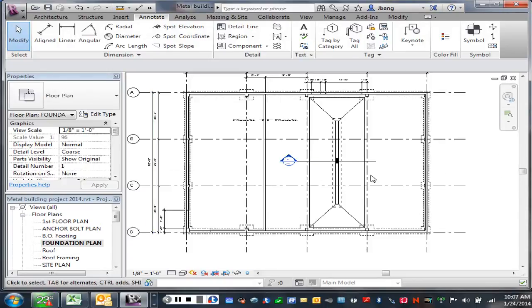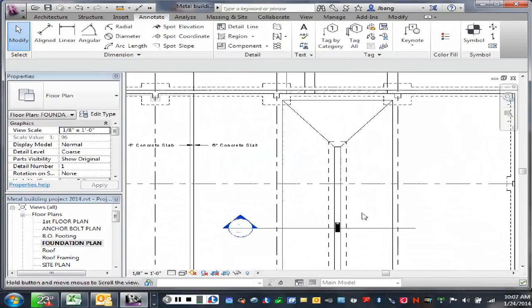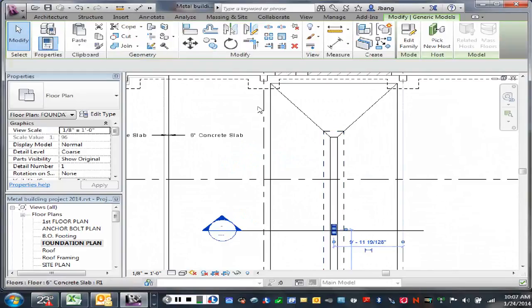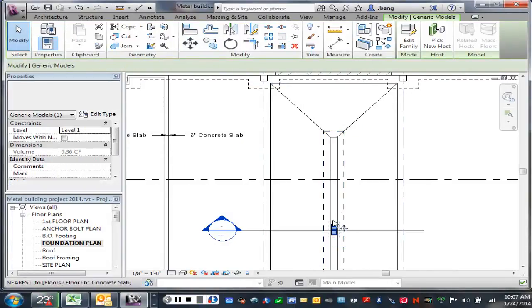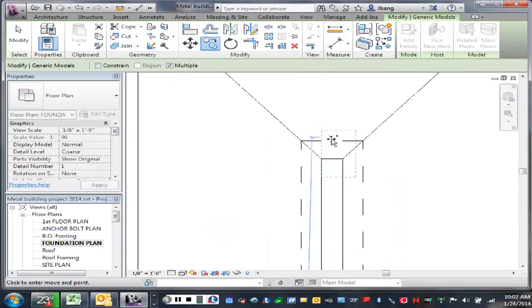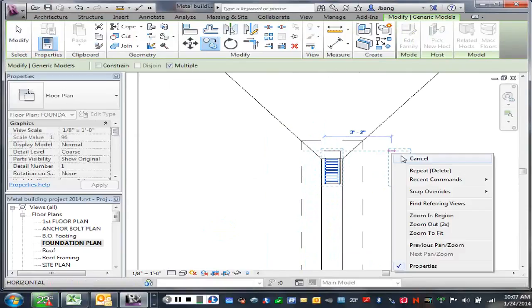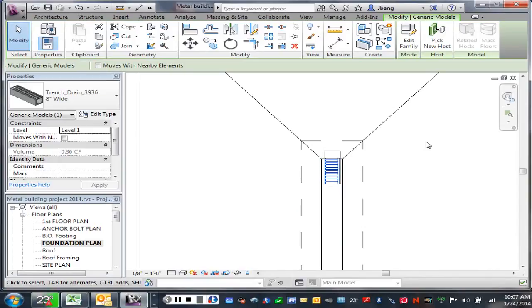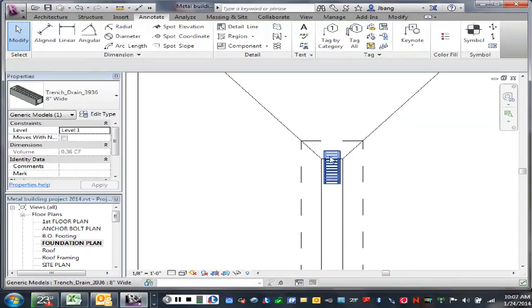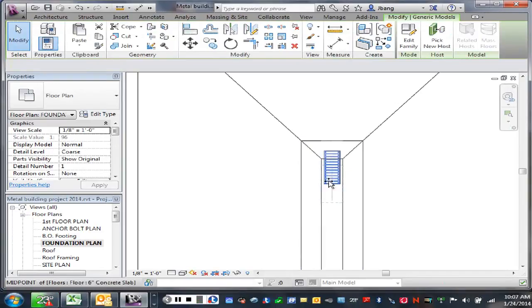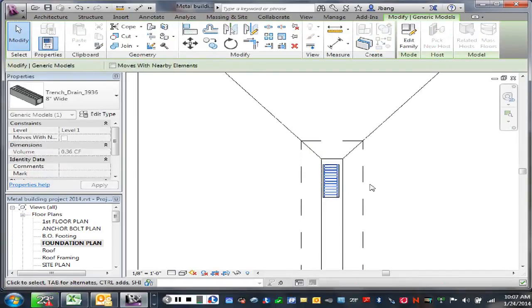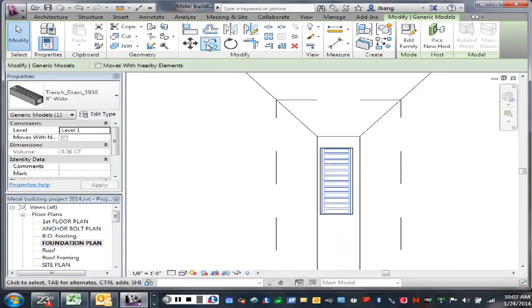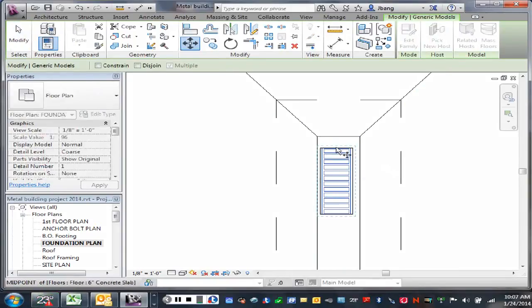And then, of course, I only have one in there now, and I'd have to copy more into it. I know what's going to happen: I'm going to copy one from here, and you're going to end up with something like that at the end, because it's not going to work out to your even 2-foot increments. If that's the case, just don't put that last one in. It would be all right if this last one was down a little bit, right? So if there was a little flat spot there, that'd be okay. Okay, so just make sure you get even numbers.